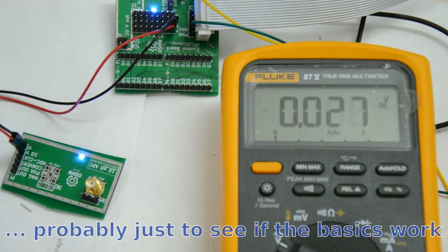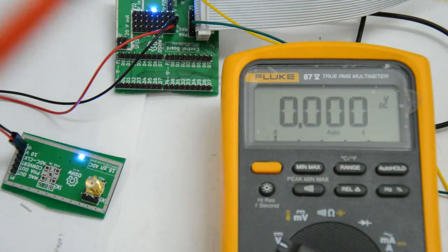I can do that because the multimeter has a pretty high impedance, but it's not infinite. So I'm connecting one end of the multimeter to the 5 volt supply, and the other end to that input, and that should charge that capacitor. If I connect one end to ground, it should discharge that capacitor.